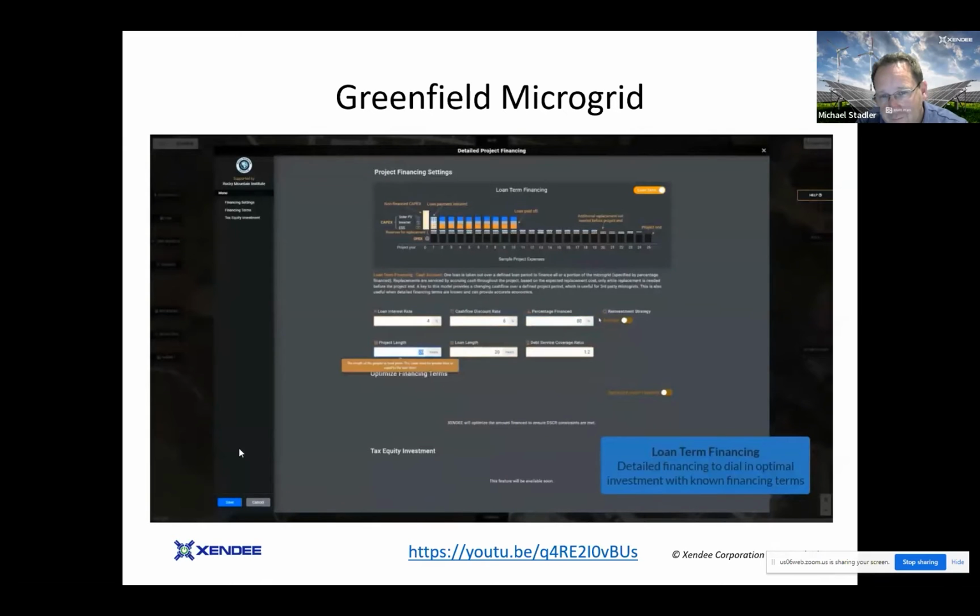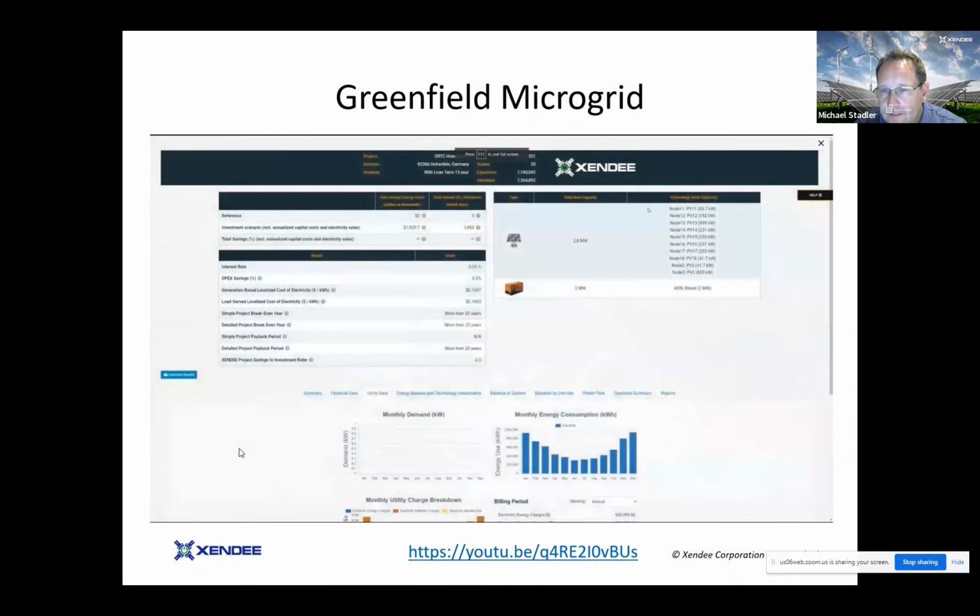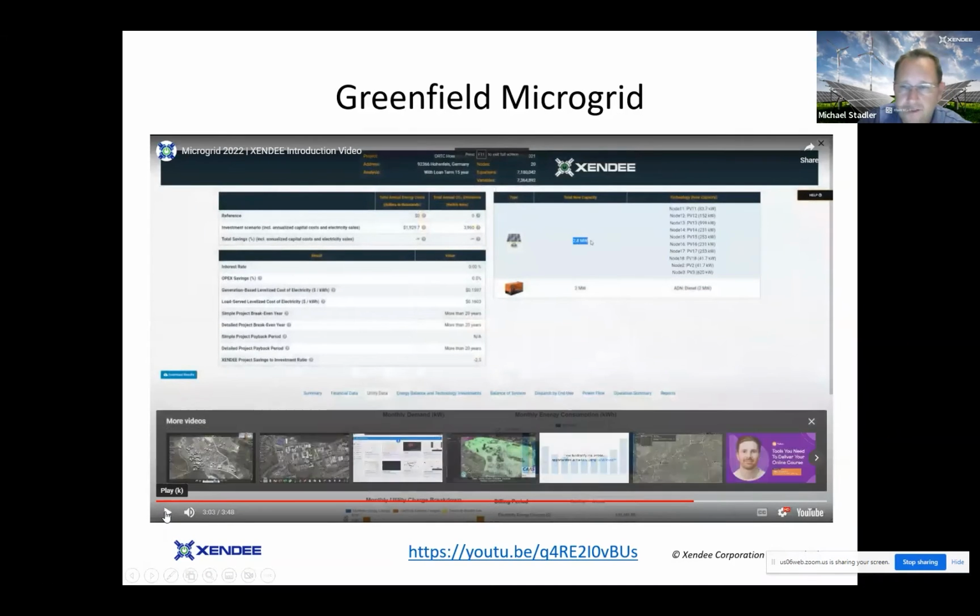And the net present value approach can be tricky if you have technologies with very different lifetimes. Let's say you want to compare a diesel generator with a PV system or something like this, then you might actually change your outcome, because if you have, let's say, a project lifetime of 20 years, then you might favor technologies which fit nicely into this project lifetime. And as you can see, the battery is gone. We have way less PV, and it's in favor now of the diesel engine.